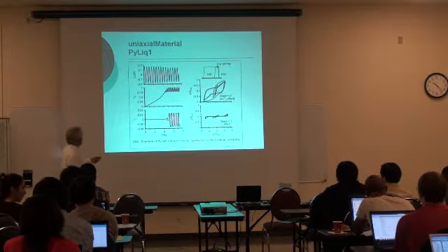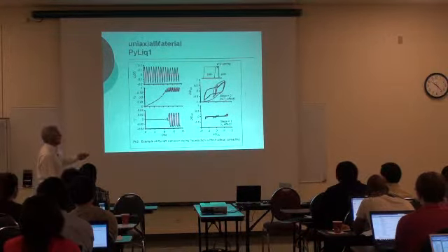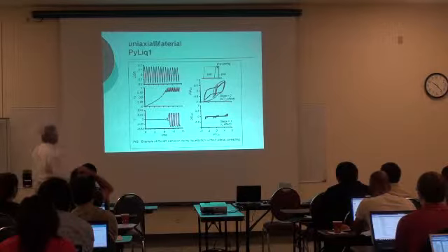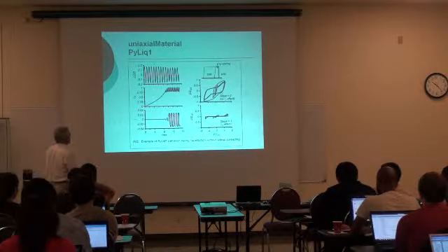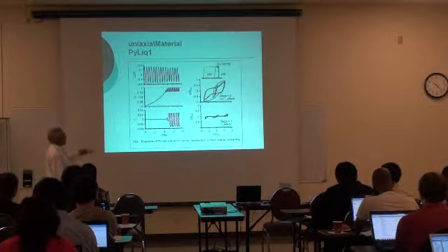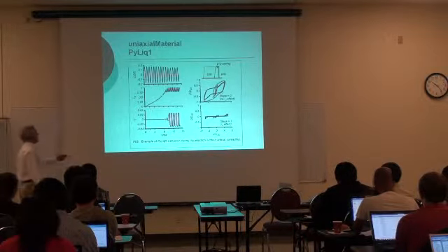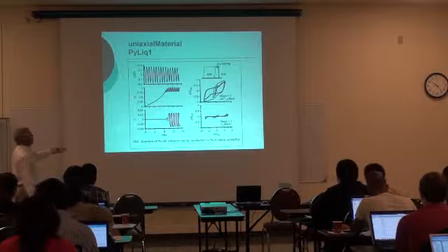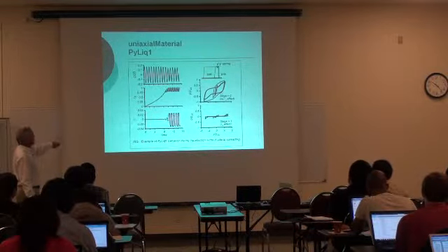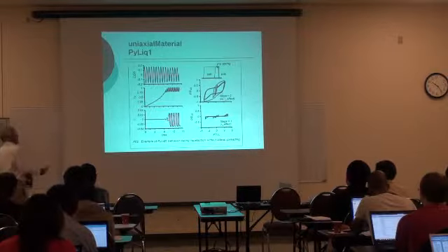And that's a situation where you see that you have a soil element connected to a pile with one of these PY springs for liquefaction, and we apply this cyclic stress ratio. You see how the pore water pressures increase. When the pore water pressures get to a level that is equal to the initial confining pressure, then the pore water pressure ratio goes to 1. And when the pore water pressure ratio is equal to 1, we say that we have liquefaction.